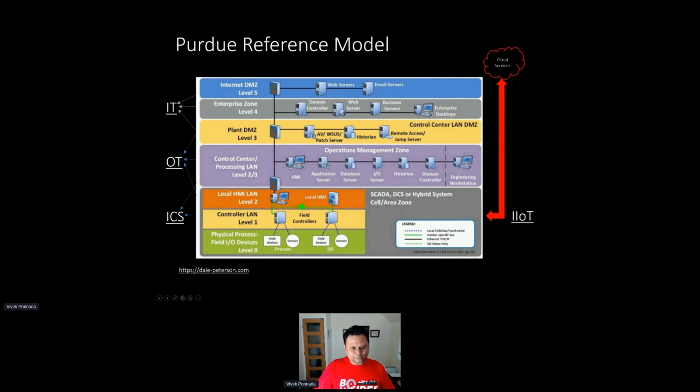And then, of course, you have this level two or level three, where you have these same kind of human machine interfaces, but for a wider area network. So maybe this covers more than one site. Maybe there is a historian that covers more than one site. And maybe these days, even a domain controller that has multiple sites under it. And then these engineering workstations are those that are used to program these controllers. And so you download logic or code from these EWS to the field controllers.